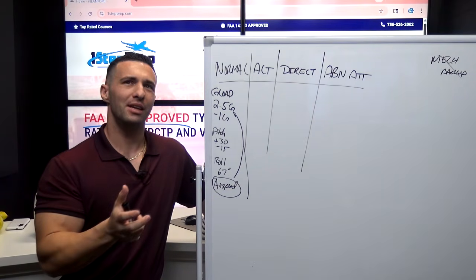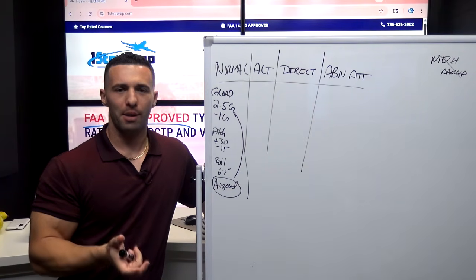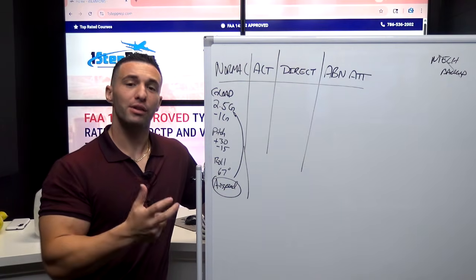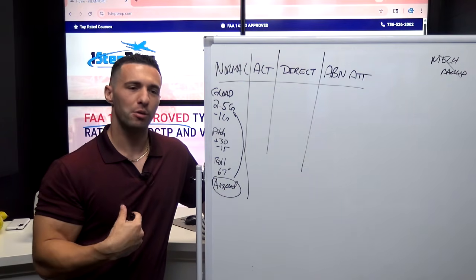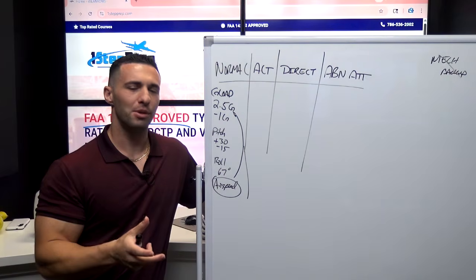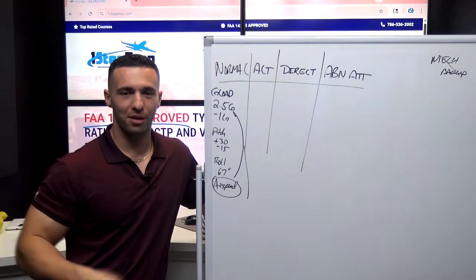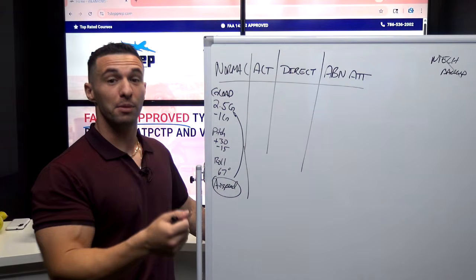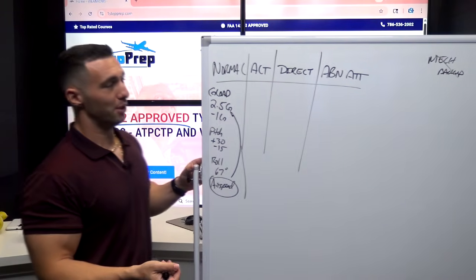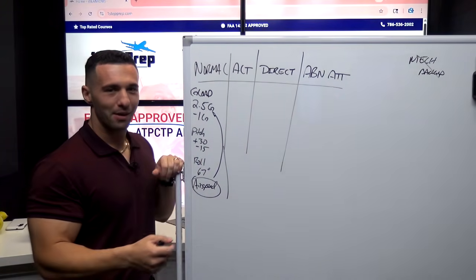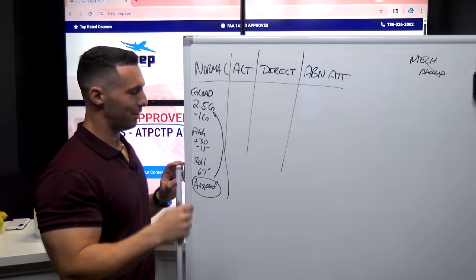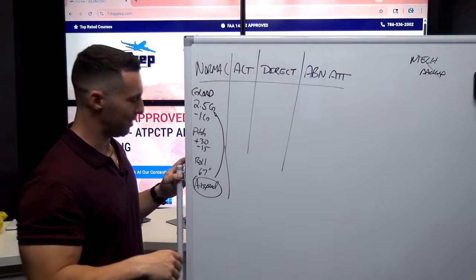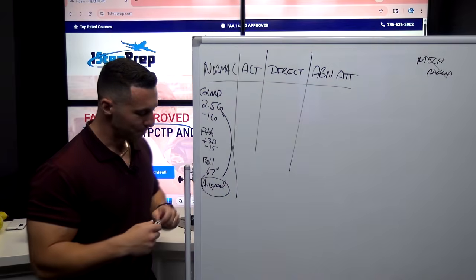So basically, Airbus did a good job, I would say, in my opinion, of installing these protections that very much work in our favor, but then also limiting them to some degree so that they don't completely overpower us and put us in a position where we can't even really put effective inputs to recover the jet, which is really why in a normal attitude law, it gets rid of all protections, which we're going to look at later on. At least temporarily it does. Anyway, so that's your airspeed protection.